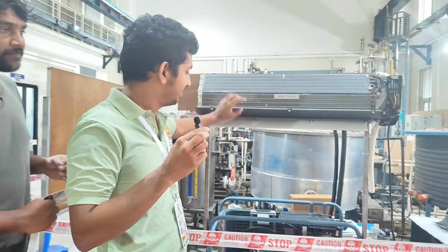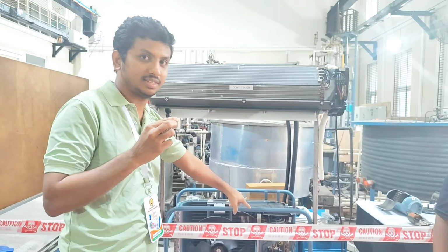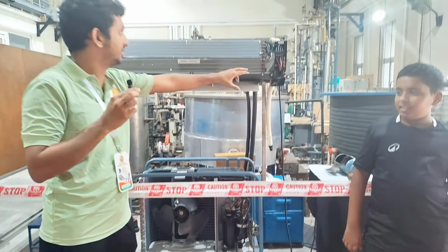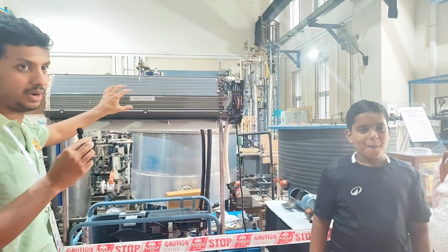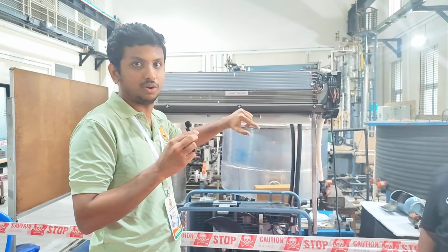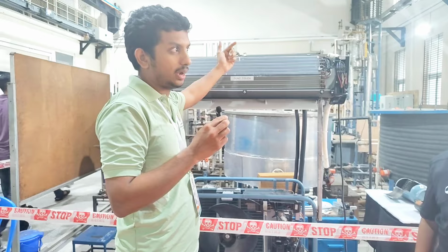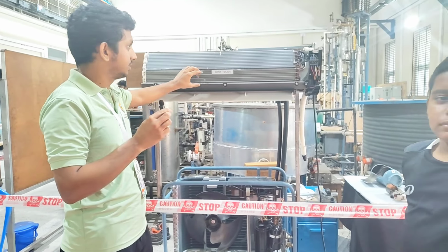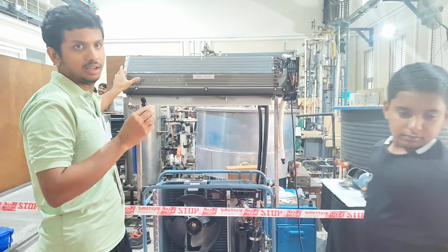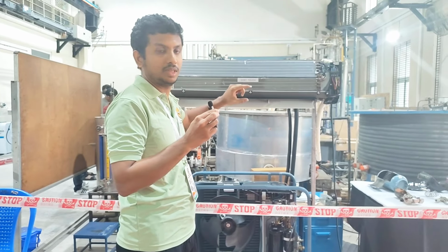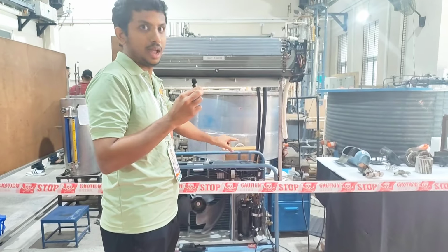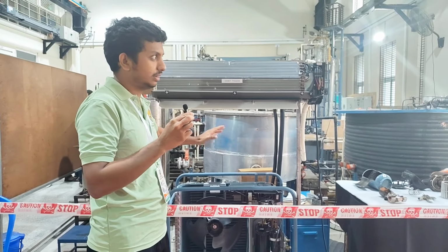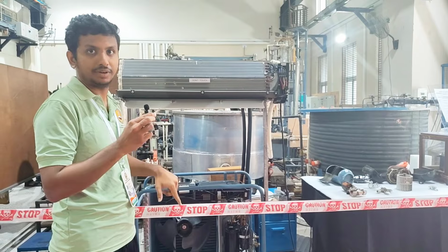This is the evaporator, this is the condenser, this is the compressor. These are the major components of the refrigeration system, where the refrigerant flows through these pipes and travels across this evaporator, where the refrigerant converts into gaseous form, and the atmospheric air is sucked in here and comes out as cool air. After traveling through these three pipes, the refrigerant goes to the compressor again. From the compressor outlet it travels through the condenser, where it rejects heat and converts into liquid.